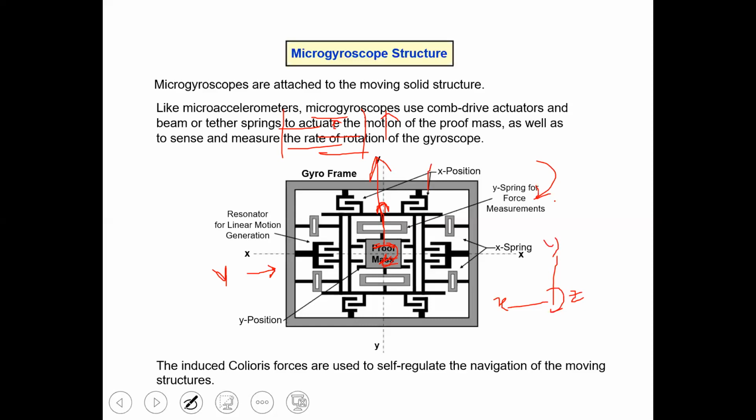Resulting, we can relate that capacitance with the angular rate that is coming onto that, right? Here in this one, these are basically the drive electrodes. So when the potential difference is applied, electrostatic force will be generated. This is a fixed one, and this is the moving one. So the fixed one will pull the moving one with certain velocity v. So this is how we can go for a gyroscope, for the micro gyroscopes. So here we end chapter 2.